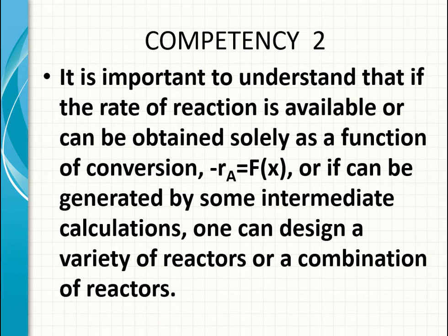It is important to understand that if the rate of reaction is available or can be obtained only as a function of conversion, that means minus RA equals a function of X, or if it can be generated by some intermediate calculations, one can design a variety of reactors or a combination of reactors.